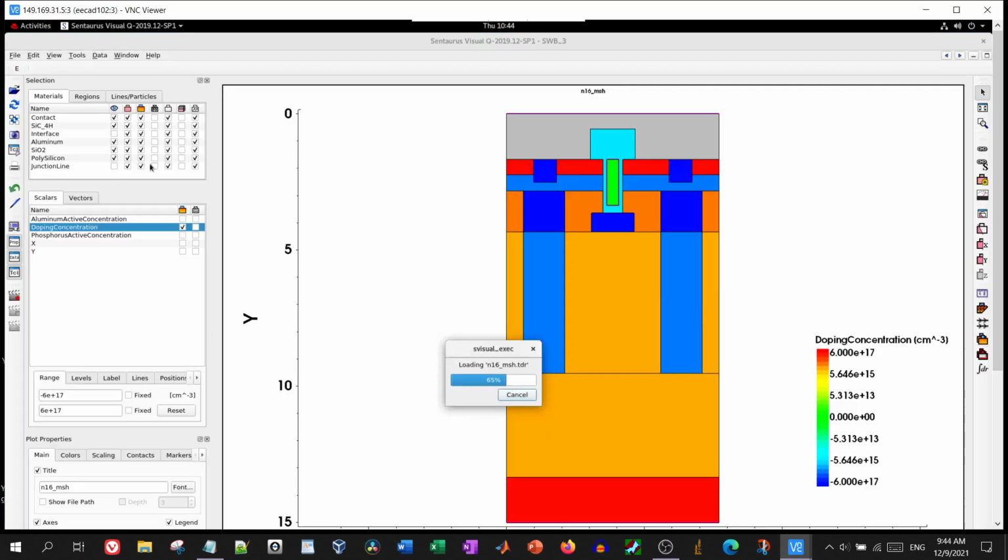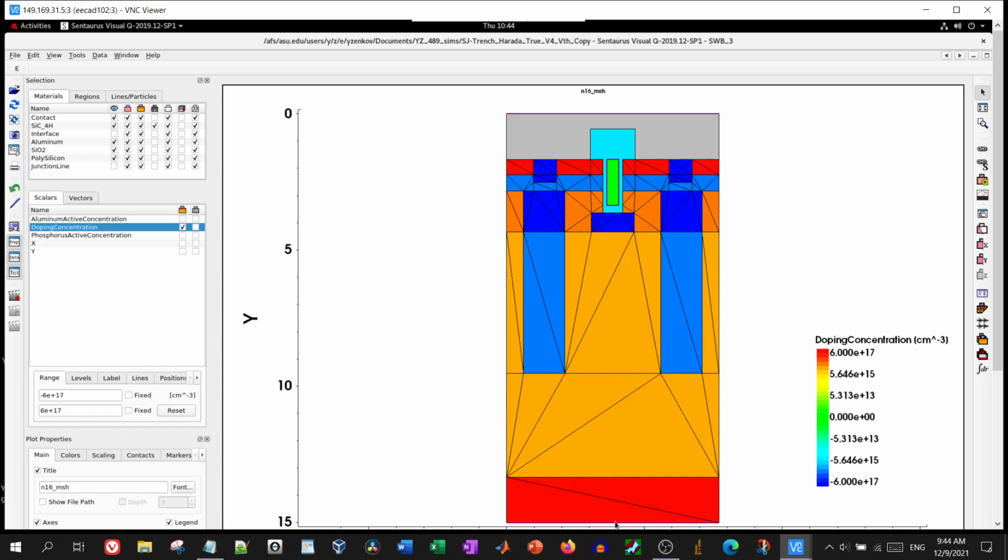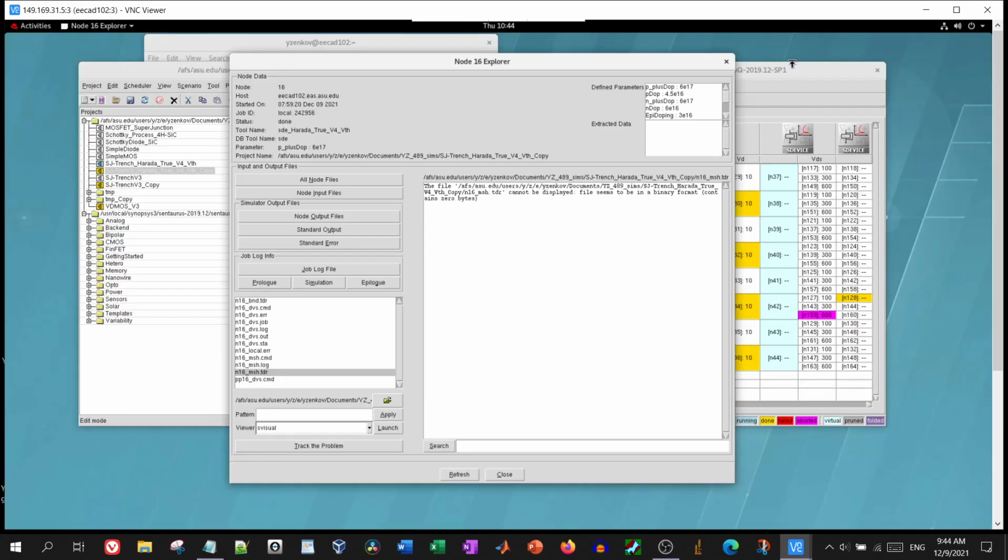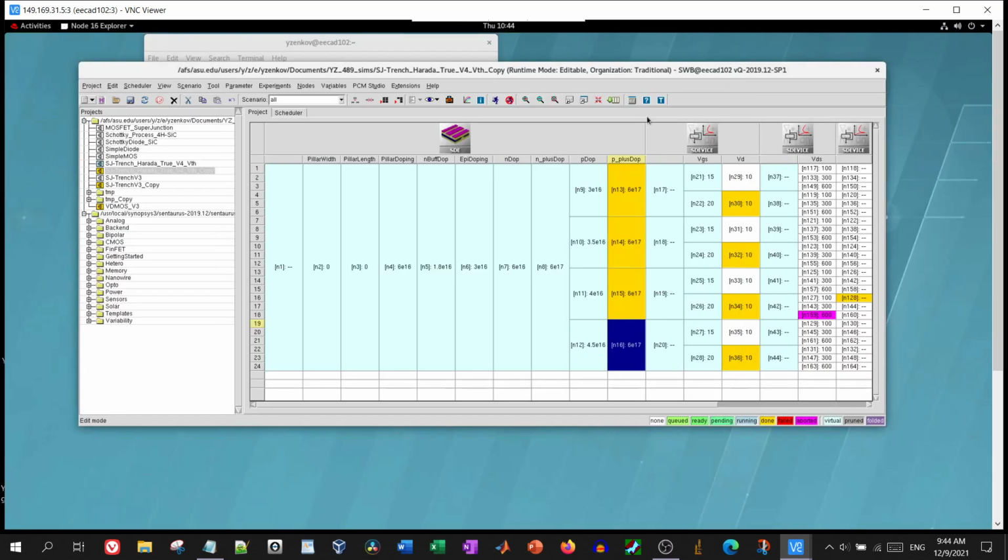and open it a second time. This right here represents meshing. By default, it's turned off, and then when we turn it on, we can see what it is. And as you can see, there's barely any resolution here. It's just a couple triangles per region. This is how it's going to be by default, and it's going to be absolutely worthless in terms of making good results. However, you should not start meshing right away. You should instead make your structure, then run your electrical simulation, see where there is insufficient resolution, and then set more meshing.